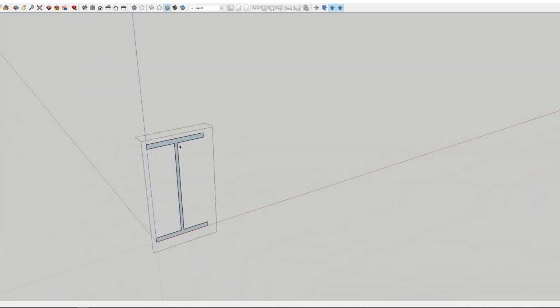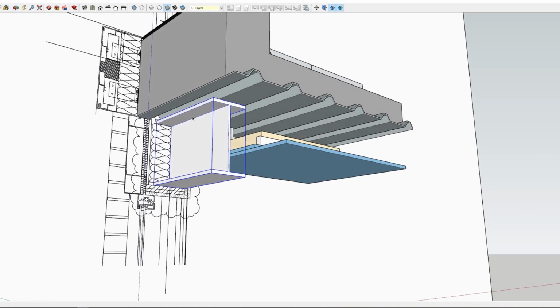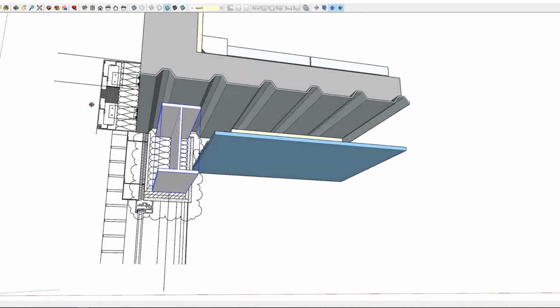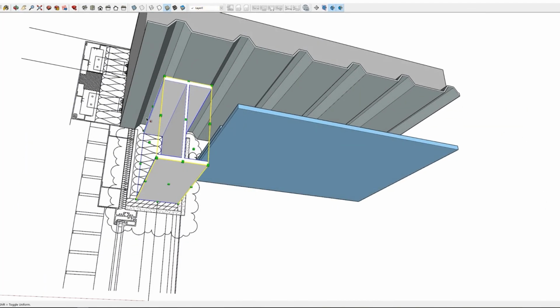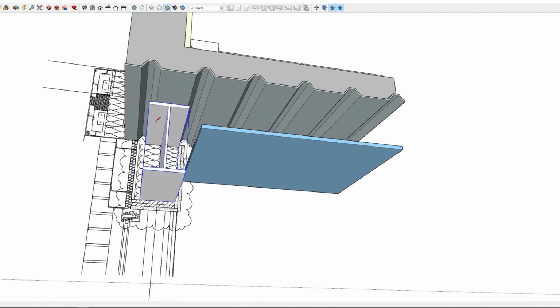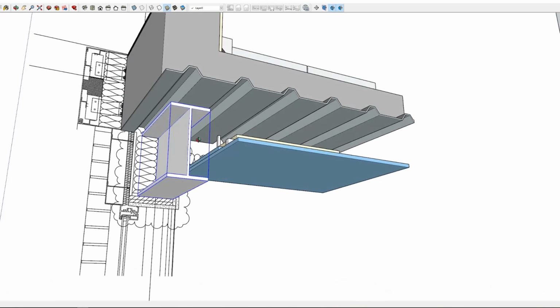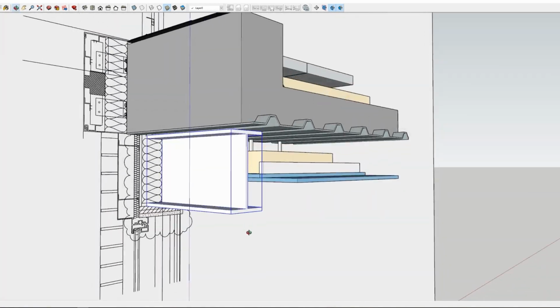So you've got your beam there, and that's picking up the edge of the deck. And you're allowed an element, I forget what the figure is now. I imagine we've worked to it, 100. So it must be. You're allowed 100mm beyond the beam to project that deck, but as dictated by the engineer, obviously.